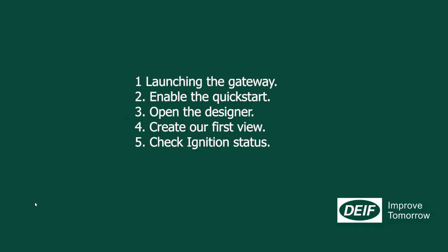In this video, we'll walk through the Quickstart experience in Ignition, running inside a Podman container on a DEIF PLC. We'll start by launching the gateway, enable the Quickstart project, then open the designer, create our very first view, and finally check system status and memory settings.